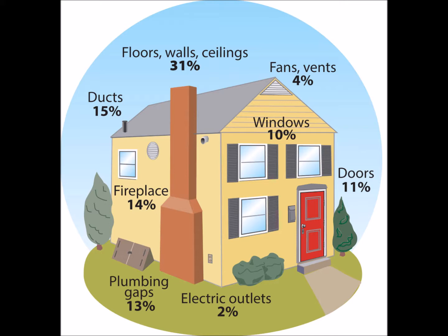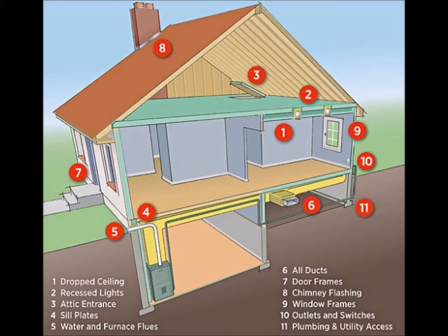Therefore, the use of an interior air barrier system in cold and very cold climates is preferred and may be combined with a warm-in-winter vapor diffusion retarder. A viable approach in such areas is the airtight drywall approach, used in conjunction with an interior vapor diffusion retarder layer, such as kraft-faced batts or VDRs, vapor diffusion retarder paint on drywall.